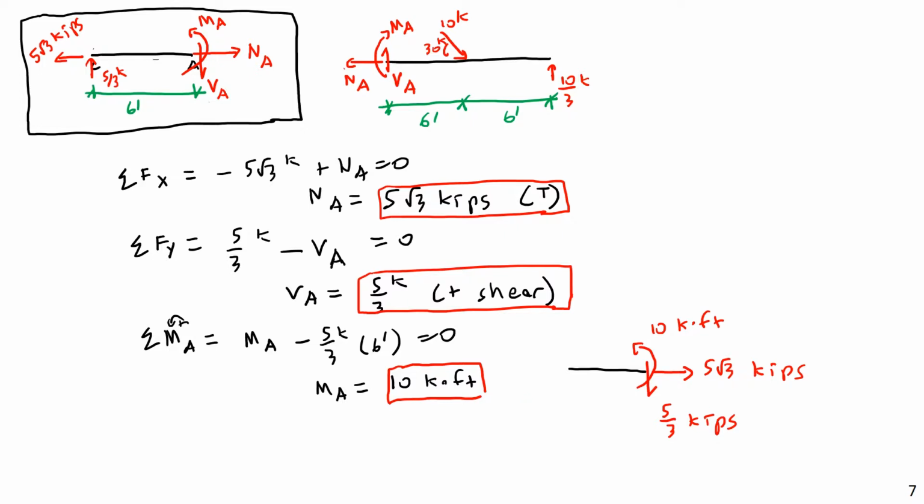So for example, in reinforced concrete or steel design, you'll use these forces, and you'll often use statics or more advanced techniques to get the internal forces. But once you have them, you'll use the various things you learn in upper level coursework to learn how to design a cross section. What I mean by that is, how big is it? How wide should it be? How thick should it be? How strong should the steel or concrete be? All of these are going to be dependent on the actual internal forces you calculate.